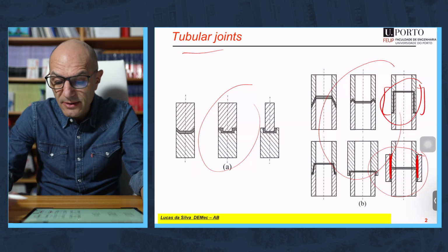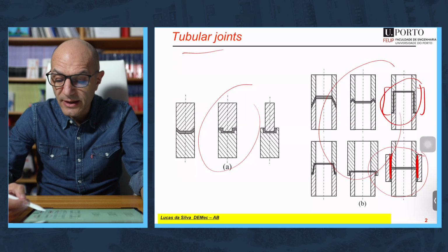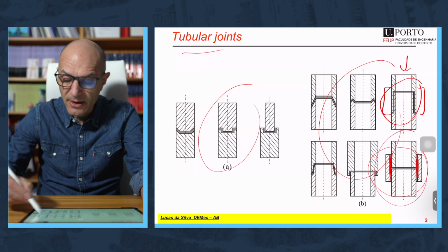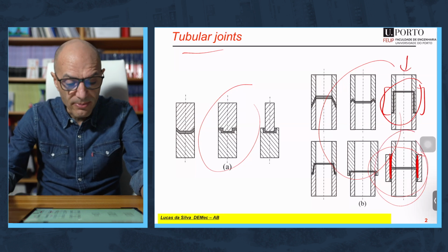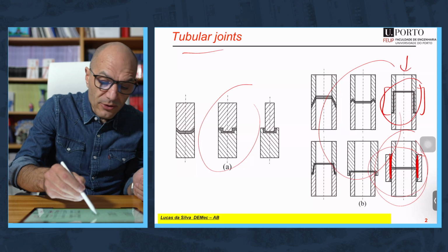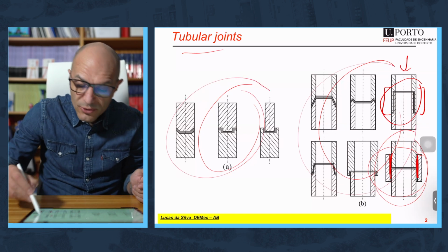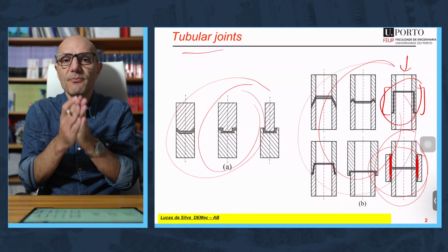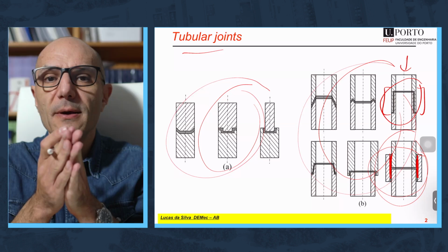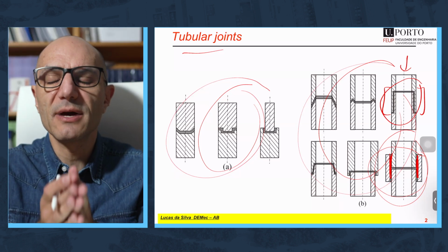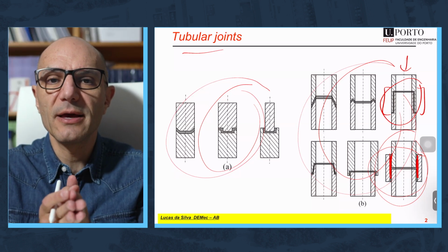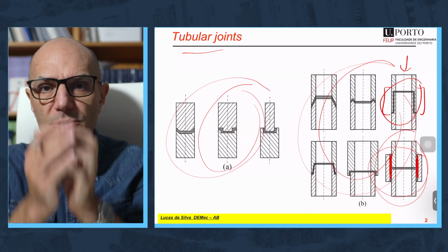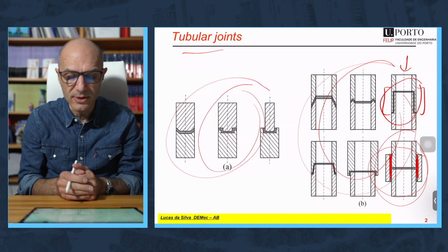The problem is some configurations, of course, they are ideal and they would work fantastically well, but in terms of production, this is arguable. Obviously, this is much simpler to apply. But again, whether you have bars or tubes, I remind you this rule of thumb: make sure that you increase at maximum the bonded area loaded in shear and you reduce the peel stress.